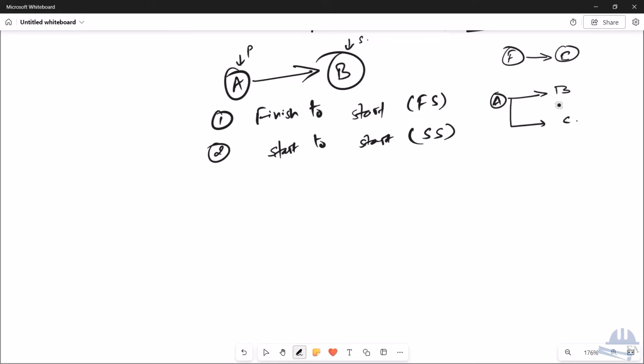For example, you do the mobilization, and after that you do the excavation, or let's say the foundation work. And the foundation work for the building and also for the site development, like for example construction of any protection wall, you can do simultaneously.